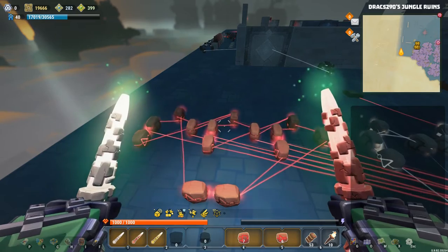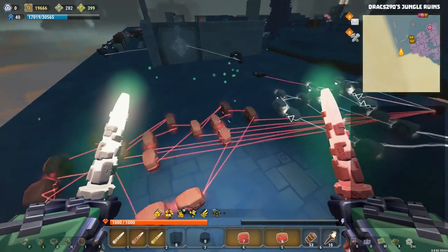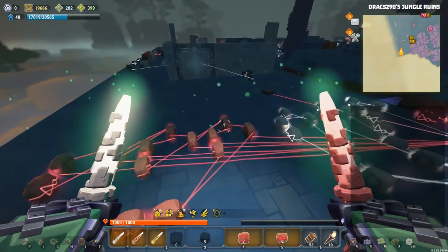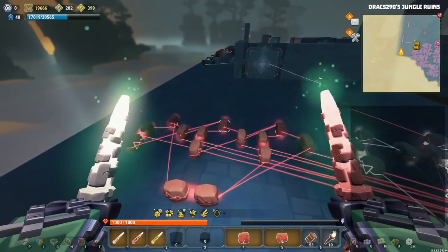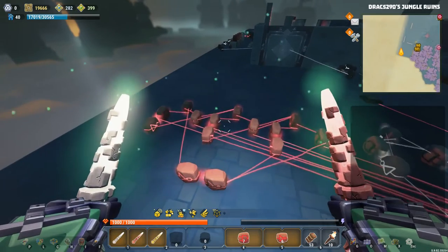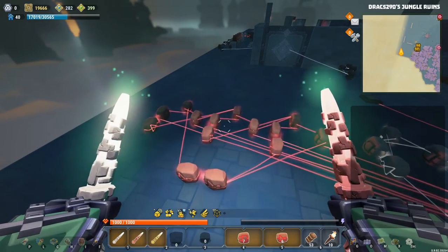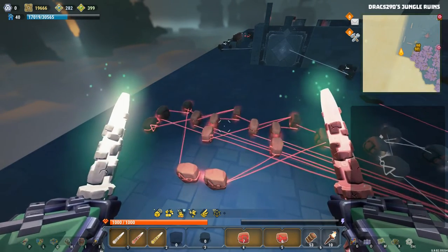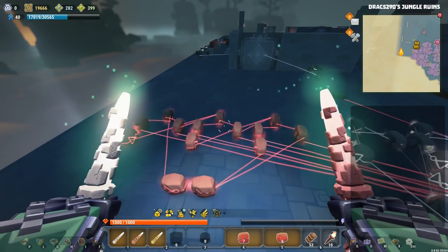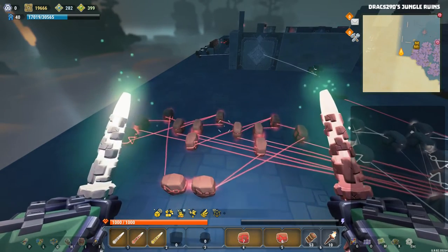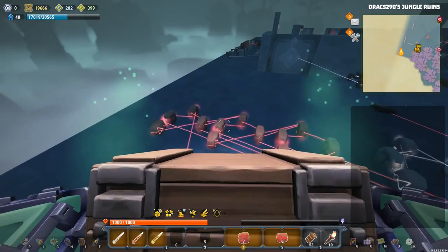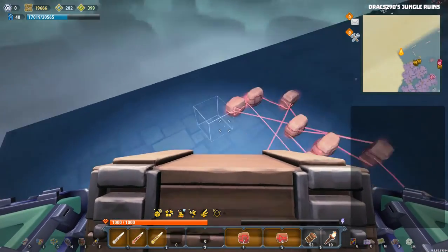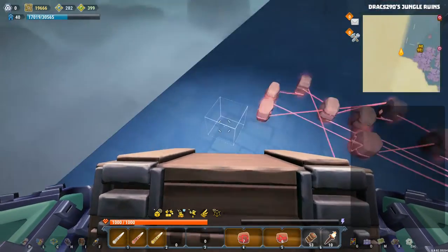And if it's all off, the same thing, nothing can happen, because this circuit works by having whatever is happening in the first latch copied into the second, whatever is happening in the second copied into the third, and so on. So if there's nothing happening or everything is happening, nothing can change in this circuit, and that makes it completely useless to us. So we really want to make sure that neither of those two things happen, and that's why we have all of these extra gates here. Now these extra gates are all about protection for the system.